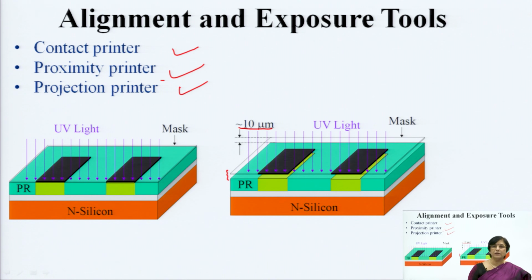But then you have another cost to pay. Please understand, whenever you have a simple shadow, the shadow of the light depends upon the position from where the mask is being placed. So, naturally the image getting formed will have degraded resolution, and it will not be an exact replica because of the gap. There can be shadow impact, and the resolution of printing will not be as good as in contact printing. So, this is the cost you have to pay. That means your resolution can get compromised.